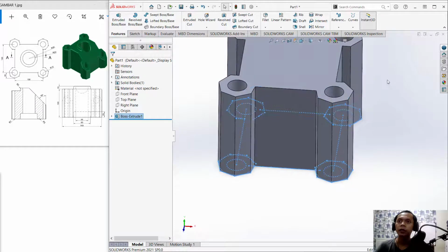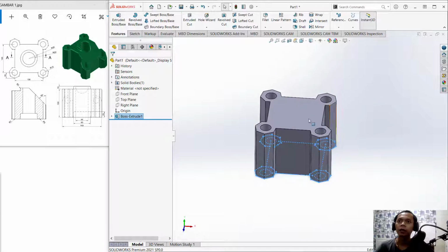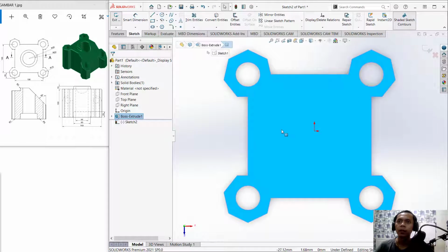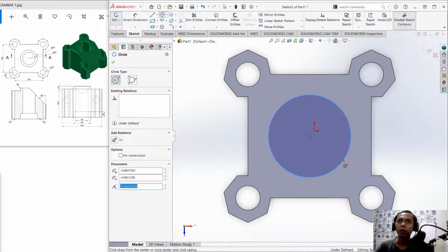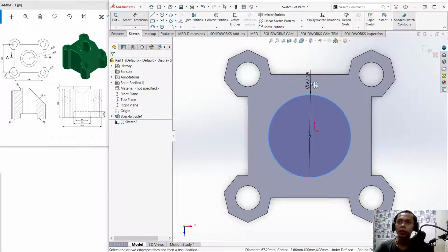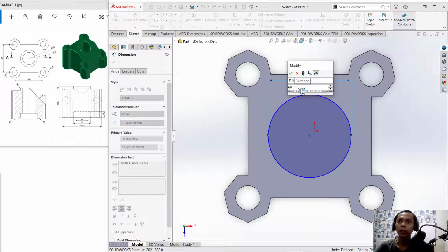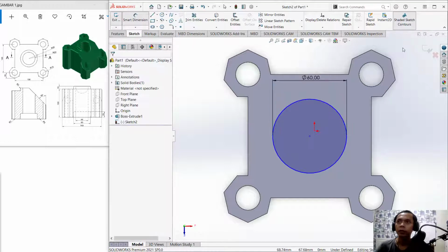Now we can select at this face. We can create new circle. You can click sketch and click sketch again. In here I will create circle. Start from center point. You can sort at this middle point, and also in here middle point, and move to the center point here. We can set in here for diameter into 30 or 60, or radius into 30. Okay, you can set for diameter into 60. Can press enter. Now we can close sketch.